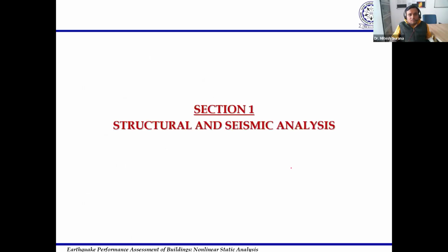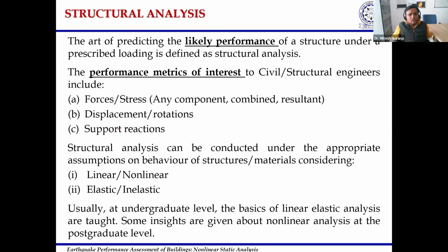Now coming to the first part of this presentation. First we need to understand what we mean by structural analysis and seismic analysis. So let us try to understand first the structural analysis. As civil or structural engineers, we are always interested in determining forces, displacements or reactions in any structure. This art of predicting the likely performance of a structure under a prescribed loading we define as structural analysis. Performance metrics of interest for civil or structural engineers are particularly forces or stresses. It can be only one type of force, for example bending moment, shear force or axial force. It can be all types of forces. Similarly, stresses can also be a single type or uniaxial stress. It can be a resultant of multiple stresses acting on a body or a system.